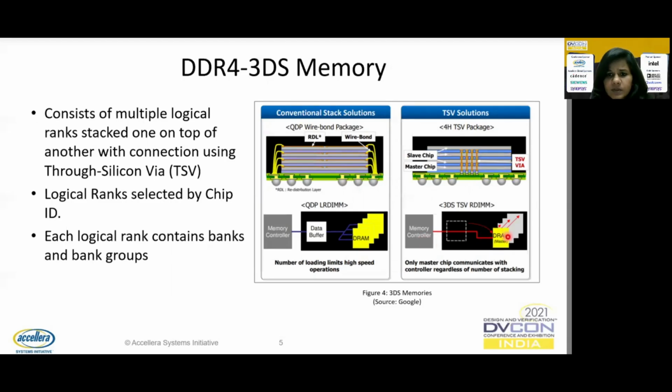The master chip is the only interface on the stack which communicates with the memory controller over the data buffer on the LR DIMM. TSV is an effective solution for achieving more capacity in less unit volume without adding bus loading as compared to the conventional solution.